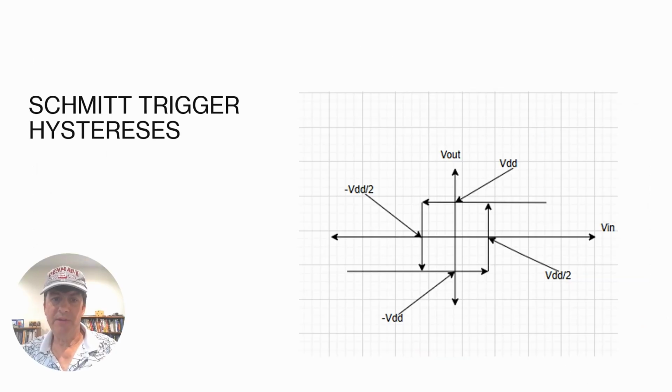In the diagram, hysteresis is depicted. Hysteresis means the switching threshold is different depending on the direction of the input voltage. A rising signal switches at a higher threshold, while a falling signal switches at a lower threshold. The biggest reason hysteresis circuits are used is for noise immunity. Hysteresis prevents chatter, or rapid switching of the output, when the input voltage is near the op-amp switching threshold.